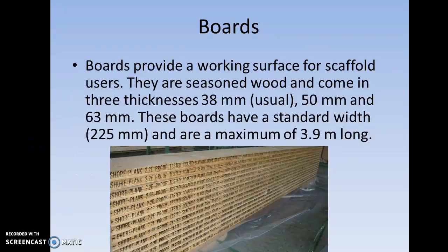Boards. Boards provide a working surface for scaffold users. They are seasoned wood and come in three thicknesses: 38 millimeter, which is typical, 50 millimeter, and 63 millimeter. These boards have a standard width of 225 millimeters and are a maximum of 3.9 meters long.